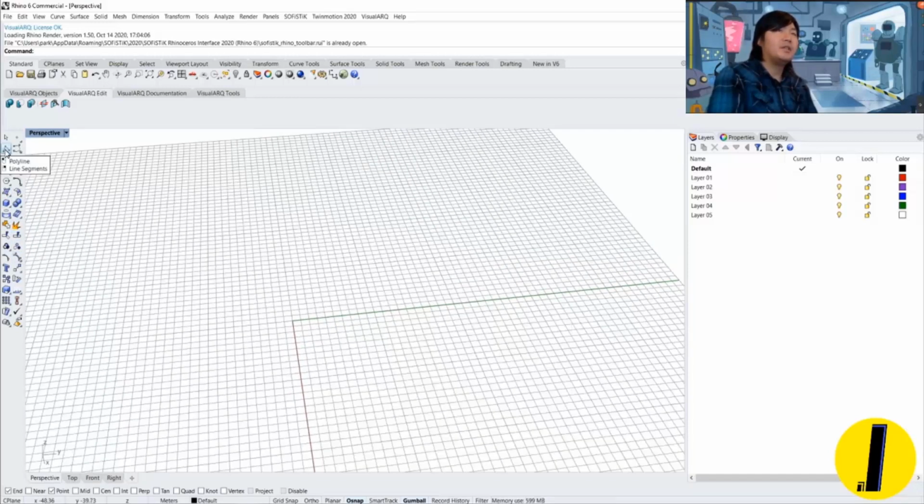The important thing is, when you hover your mouse cursor over Rhino commands, you can see two mouse icons: one is the left button and one is the right button. Depending on which button you click, you get different performance. When you look at the small triangle and click it, you can find a bit more extension of the commands, so you have more options to work with. Basically, above here these are 2D tools, and then you have surface and solid.